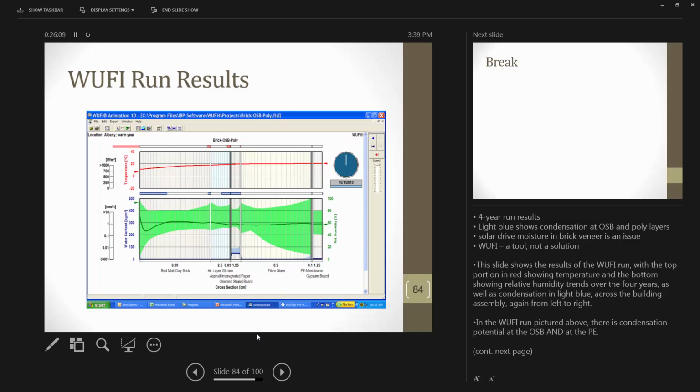But if we just add what I would say most builders use, an adequate or par air barrier to stop some of that or slow it down, we've got enough drying time. We have enough periods of time with very low relative humidity that we're not going to get excessive storage of moisture in our materials. So, does that make sense?